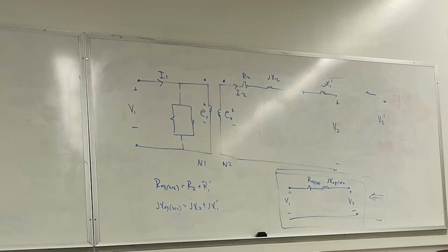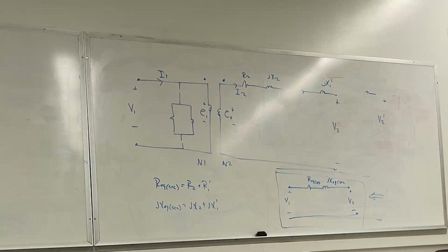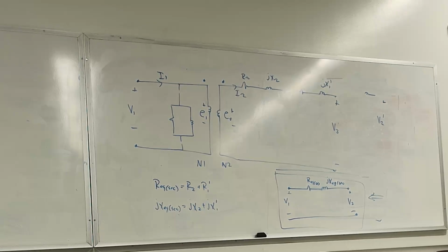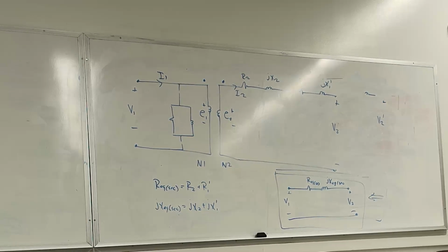But for now, any questions about how to come up with the formula? They're very simple, right? Remember, if you're transferring secondary windings to the primary side, you multiply by A squared, or the turns ratio squared. If you're transferring primary values to the secondary, you multiply by 1 over A squared, or N2 divided by N1, same thing, right? Make sense? Or did I confuse you when I said that? Okay. Yeah. Makes sense. All right. Any questions?